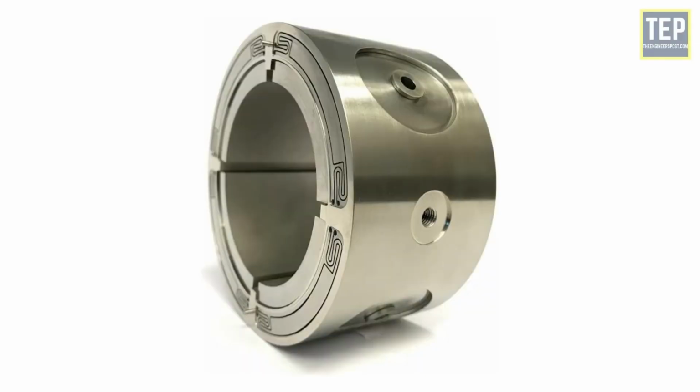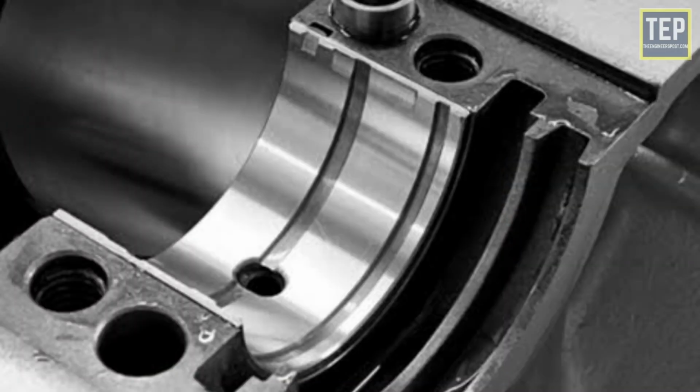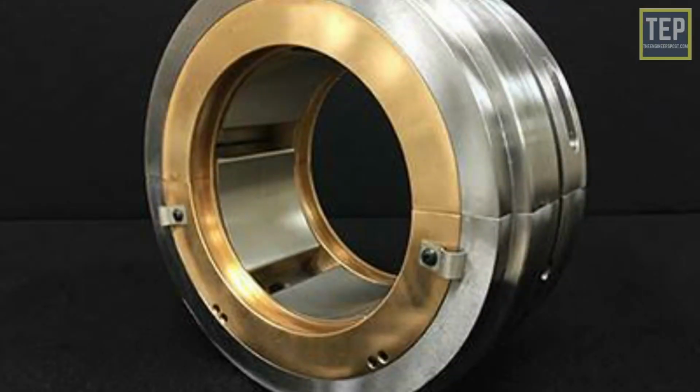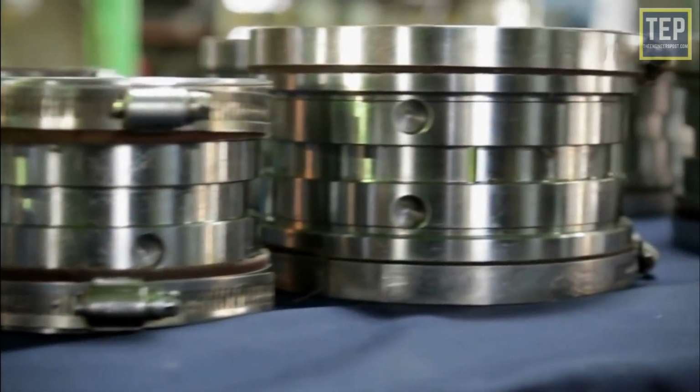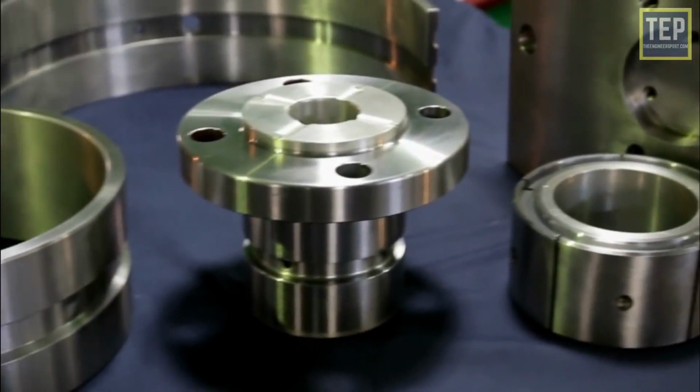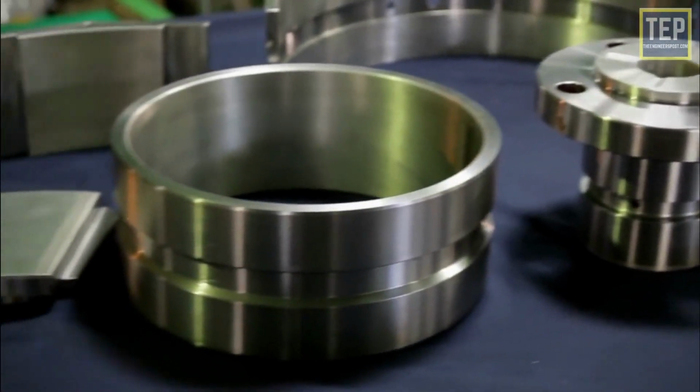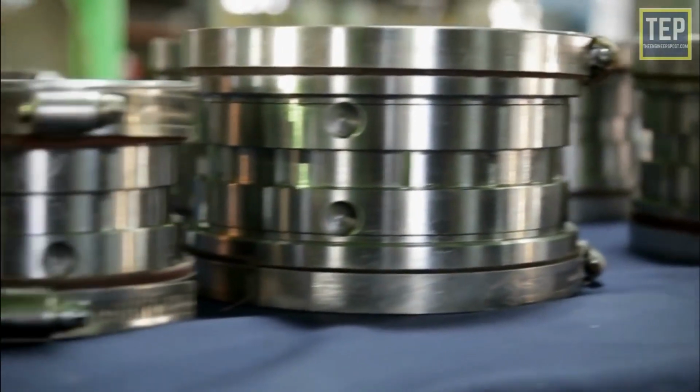Fluid bearing is a special type of bearing that relies on pressurized gas or liquid to carry the load and eliminate friction. These are used to replace metallic bearings where they would have a short life, in addition to high noise and vibration levels. These bearings are used in machines that work at high speeds and loads. While the initial costs are higher, the longer lifespan in tough conditions makes up for it to run longer.